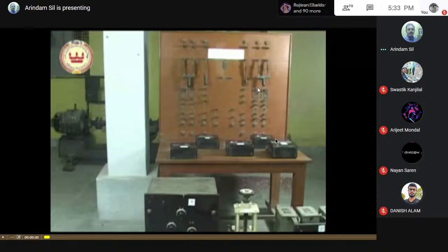So when I switch this on, when I put this handle to this part and connect it here, the power is connected across these two points, and the power starts flowing through the series RLC network and goes back. Now I have this inductor, capacitor and load box connected along with the voltmeter and ammeter, and then we start the experiment by going through the 4 conditions: VL nearly equal to VC with I max, VL greater than VC, and VL less than VC.